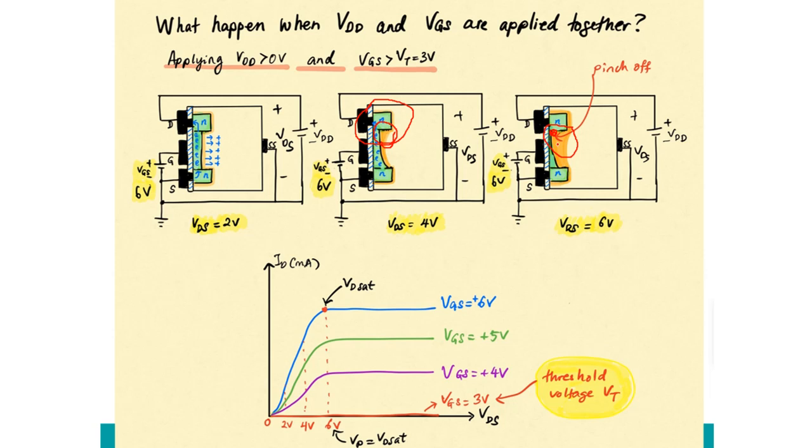During this time, the current is at maximum level and we get the IDSS, which is the saturation current. So we can see in this graph for VGS equal to 6, the blue one, when the current is increased it reaches higher and higher, and at this point, VDS equals VP. The pinch off happens here. After that, the current will maintain at the saturation level.